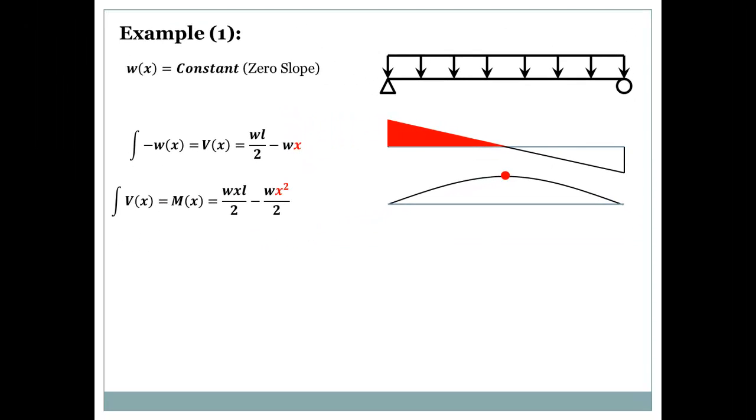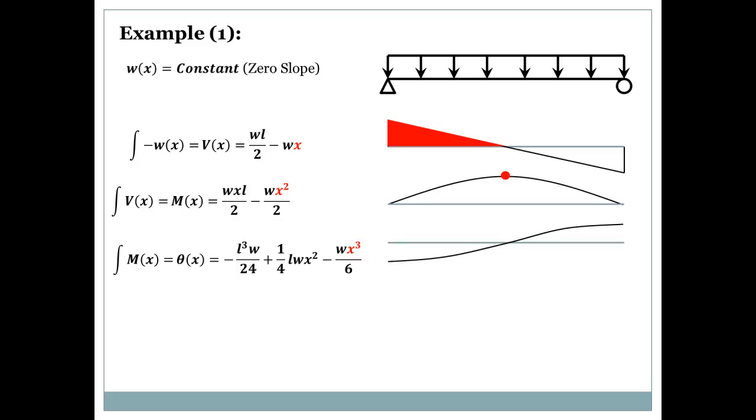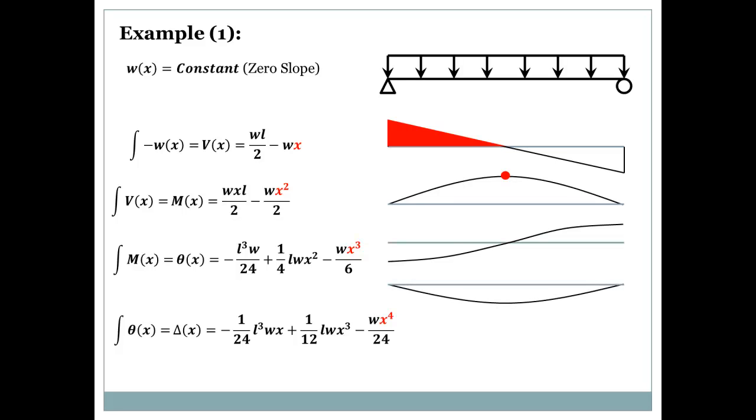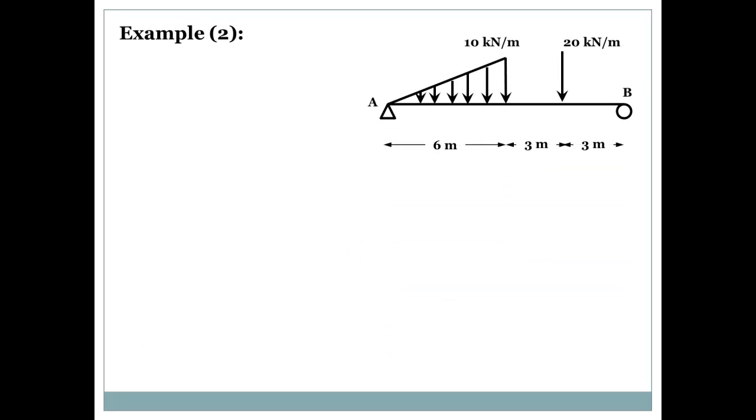Now, if you want to calculate the rotation, you integrate the moment equation and you'll get this equation. If you want to calculate the deflection, you integrate the rotation equation and you'll get the deflection. This is a very easy example to do, but the example I'm interested in is this example.